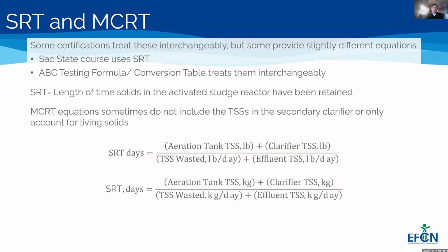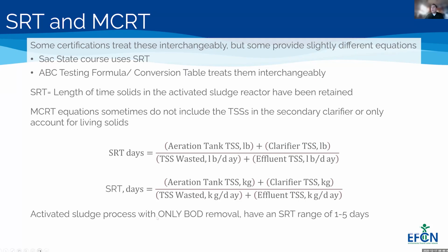This is kind of what it looks like in more of a metric system, kilograms as opposed to pounds. And then if we have more of an activated sludge process that doesn't include nitrogen, you may see an SRT range of 1 to 5 days.